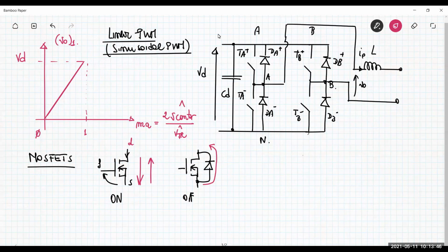Okay, for IGBTs, we have to consider that there is no intrinsic bidirectionality. And so when you have IGBTs, okay, and the IGBT is on, meaning that the voltage between the gate and the emitter is higher than a specific threshold, more or less the same voltage level that you can have in the power MOSFET, 4 to 6.